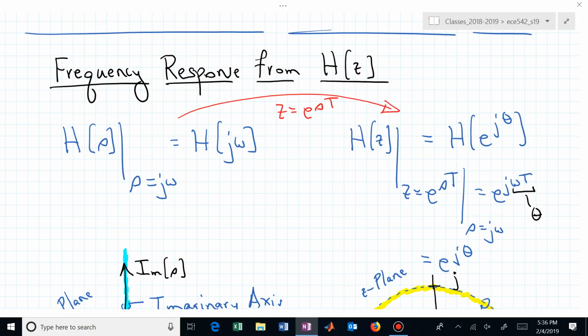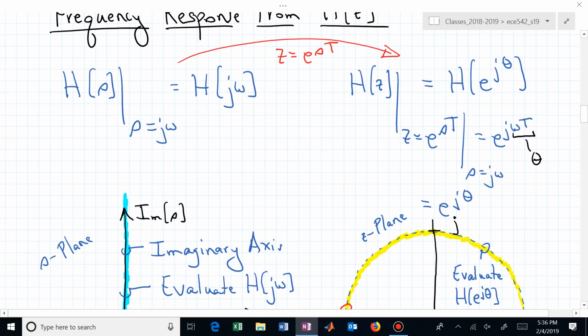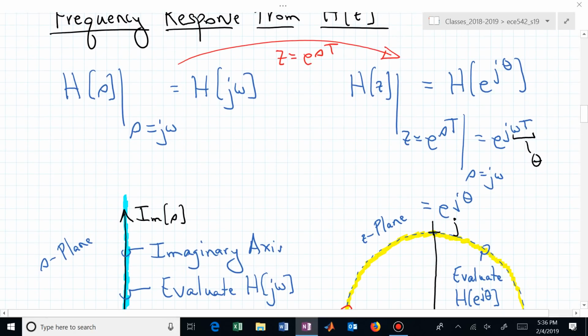We will now look at that from a slightly different perspective, in that another way of thinking of it is to generate those magnitude and phase plots. We are really working in the complex S-plane just along the imaginary axis, walking up that imaginary axis and saying, at this point, j1, what does this transfer function produce in terms of its magnitude and phase? That's how the system would respond if a sinusoidal excitation at a frequency of 1 radian per second were applied. That's how the system would alter or adjust that sinusoid as it passed through.